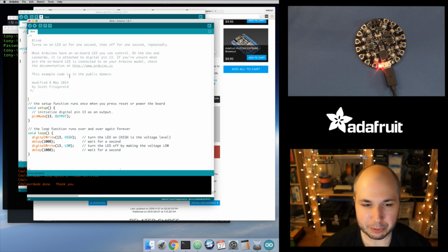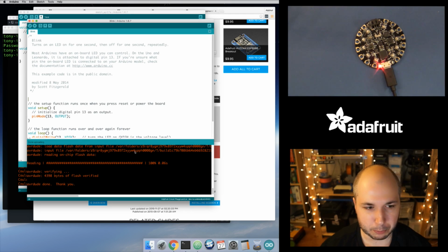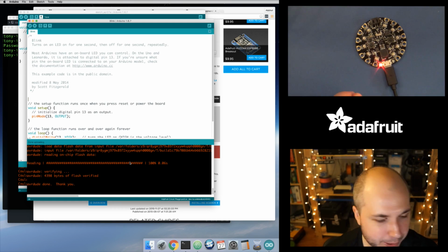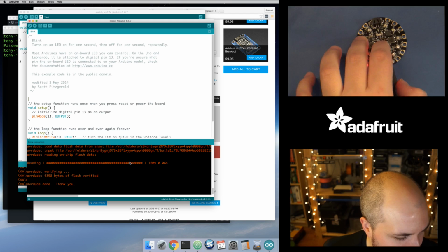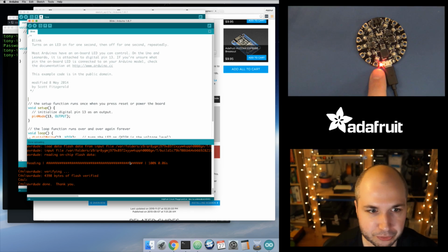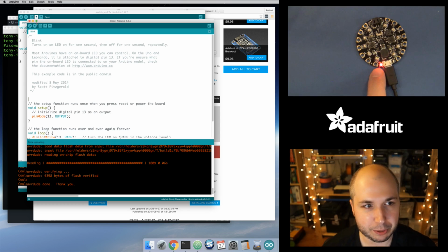I'll also show you if you ever get a failure during upload, like it says maybe it can't talk to the board or something. One quick thing to try: there's a reset button right in the middle of Circuit Playground. Double tap it, so press it twice, like you're double clicking, and you'll see the red LED starts pulsing like that. That forces it into the bootloader mode, and then you do the upload after you do that.